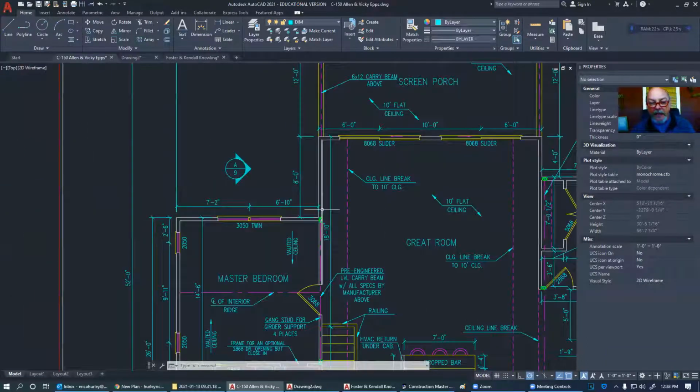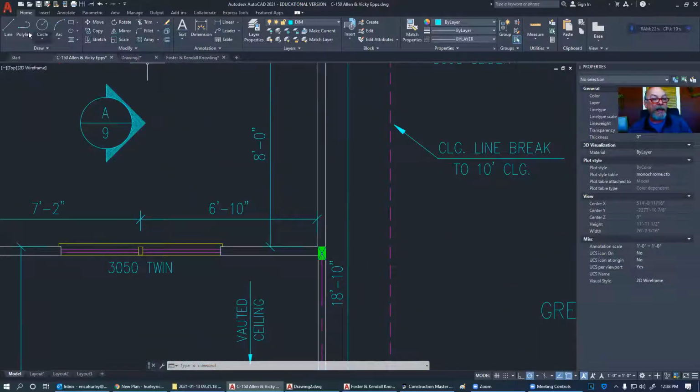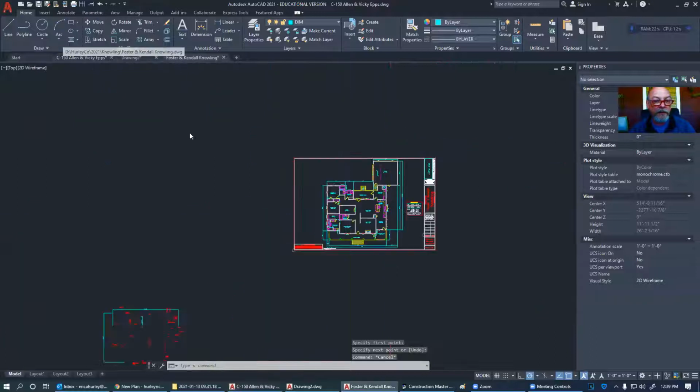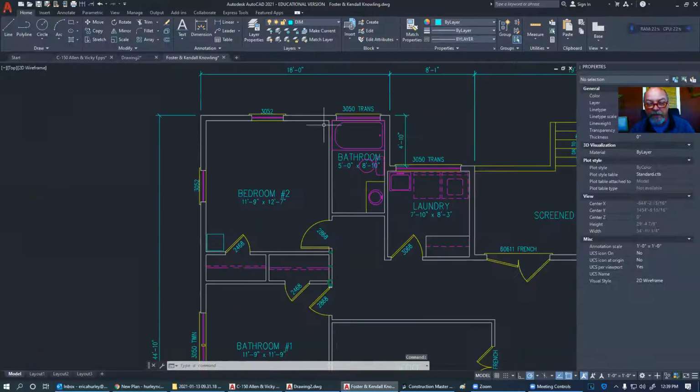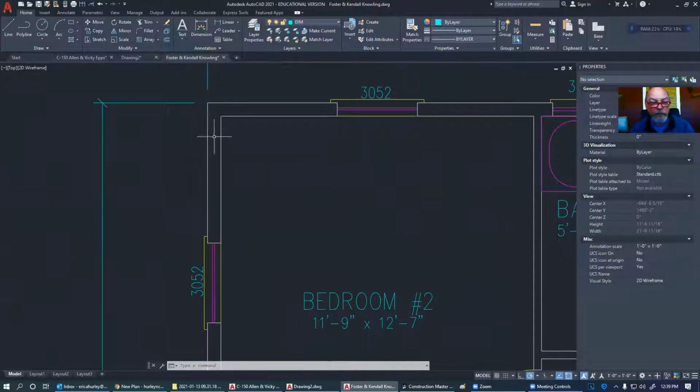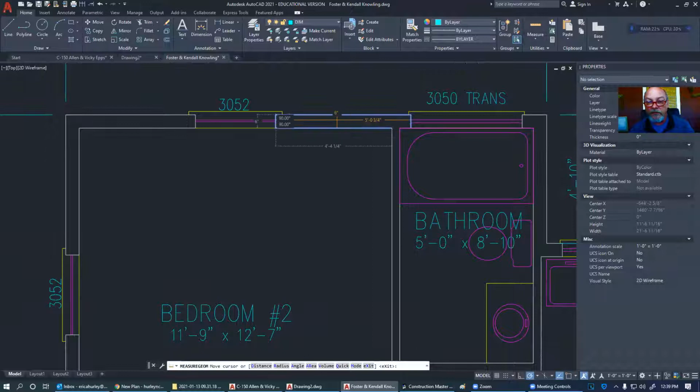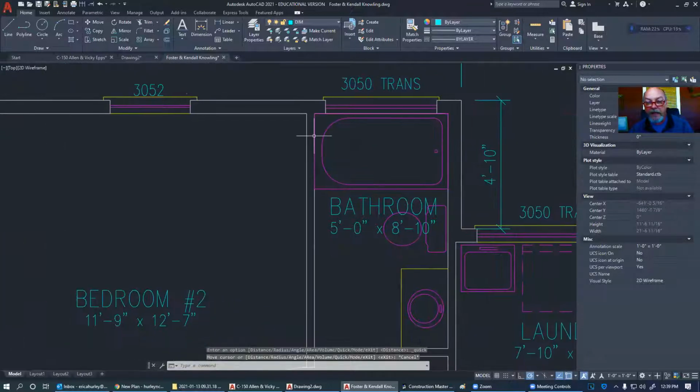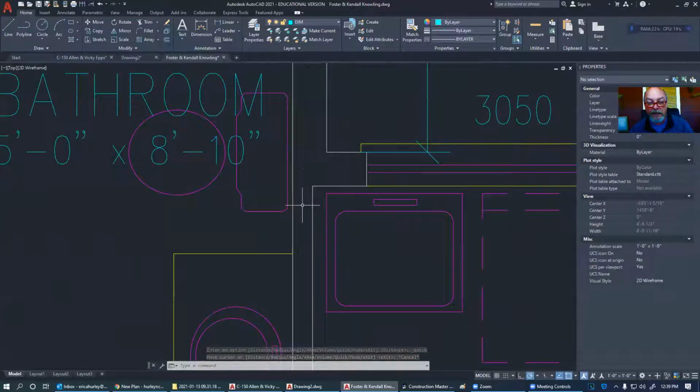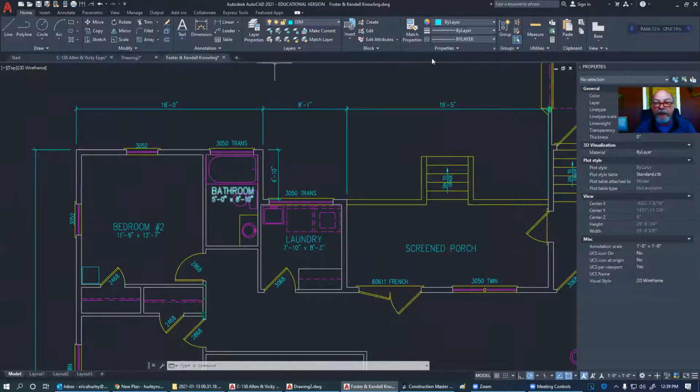Now, let's say that I've got a 2x6 wall, then I have my stud that's going to be at 5.5 inches. Actually, let me just go over here. I've got it on another drawing right there. This, you can really tell the difference in this. Here is a 2x6 wall, which is 6 inches. And then I have an inside wall, there you can see it, that is 3.5 inches. So when you're sketching out your house, you need to take, let's say for instance, I'm going to take a measurement of my bathroom.